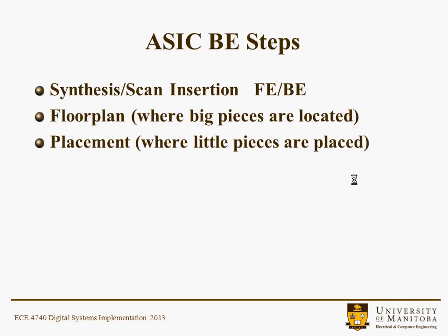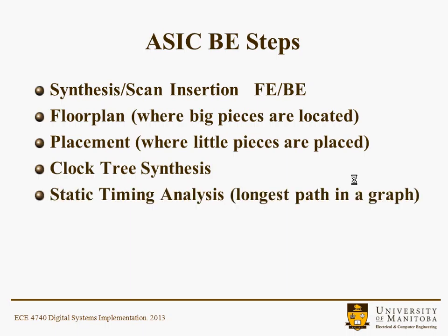and where you'd implement smaller size pieces of the design. A big part of any kind of ASIC is clock tree synthesis, and that's also a very difficult part. That's where you're trying to eliminate clock edges arriving at different times. We'll also look a little bit at static timing analysis. Effectively looking for the longest path in a graph, because that's going to tell you how fast you're going to be able to clock that particular design.